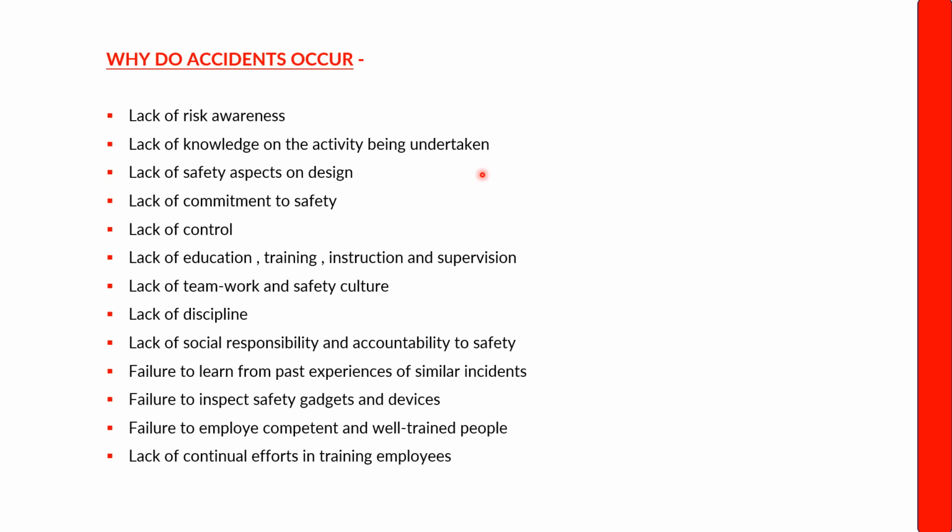When the toolbox talk is conducted with the workers, it is important to explain and review the JSA, and share with the workers the hazards noted in the JSA and the control measures. In this way, the worker will know what activity we are going to do, what the associated hazards and risks are, and what the control measures are, so that we can do our job safely.